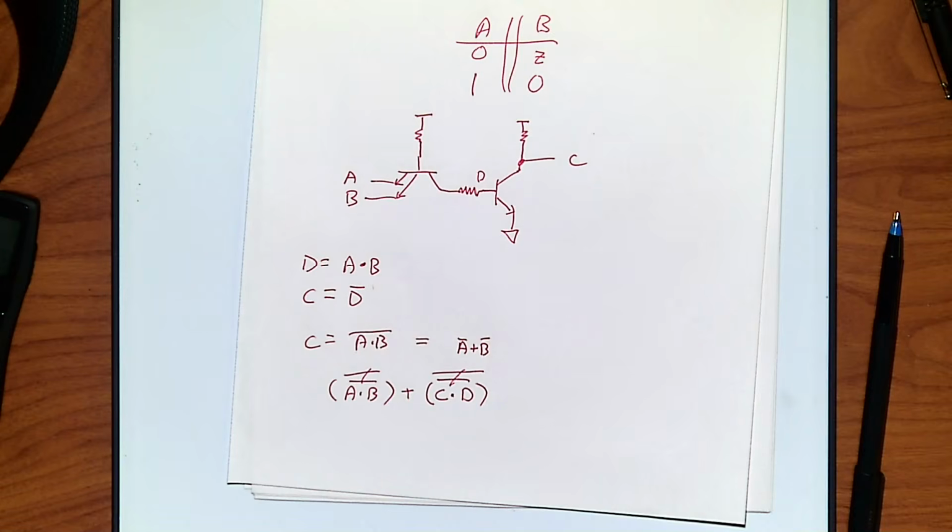But for the most part, it's better to build everything on one type of transistor because it's easier when you're building them. Remember when we did those build-up layers? At the same time, in different parts of the chip, you could be building tons of these. So it's a lot easier if you're building them and you're putting N everywhere, and then you're putting P everywhere.